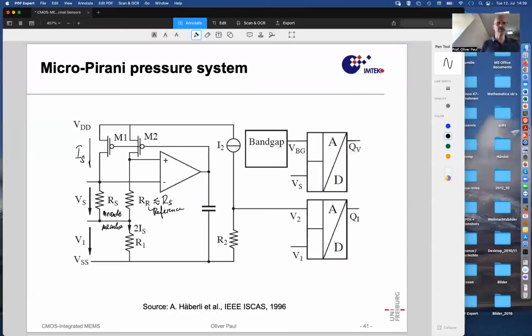I can't remember what it was. But it receives the same current IS. And this is done by a design that electrical engineers, circuit designers use universally. It's a current mirror, two identical transistors that are operated in the same point. They must produce the same currents,